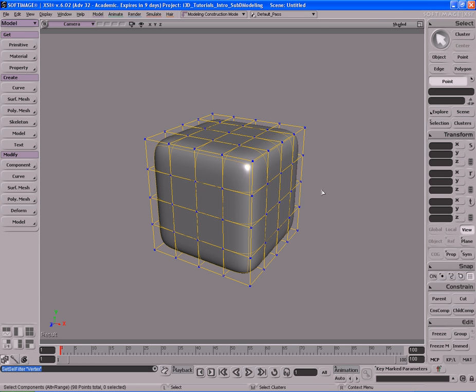I'm going to click on point, and here's our points. How do I select them? Very easy. Use the left mouse button, you can drag, and you can make an entire selection of these different points. Okay, so that's rectangular selection method.